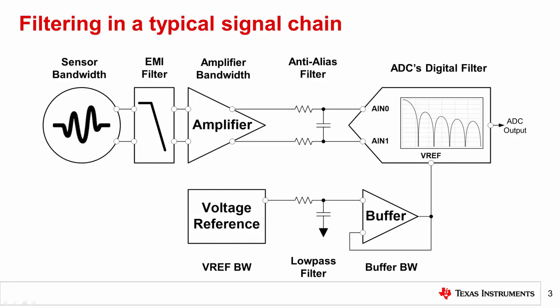Additionally, please note that the information from that module will be used to support a design example in this presentation. Specifically, this presentation will focus on a commonly used filter type that was not discussed in the previous module, the ADC's digital filter. This filter type is included in all Delta Sigma and some SAR ADCs, so it is imperative to understand how the digital filter impacts the overall system for a complete understanding of signal chain noise analysis.